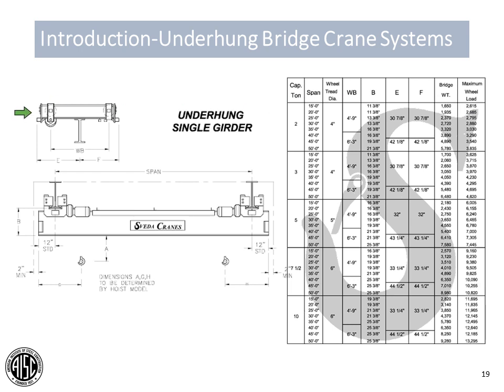This is a section view showing that end truck with the crane girder below it. And this shows the wheelbase, WB, would be the spacing of your end truck wheels. That also comes into consideration when looking at these moving loads across your runway system. There's also an elevation view shown here of the entire bridge and end truck system.